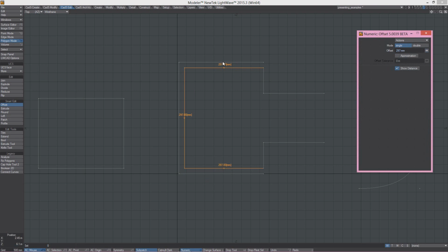Second way is to hold the Shift key on the keyboard and click and drag the mouse from left to right. That way, holding Shift, we adjust all selected or active selected handles. Because when we deactivate some handles, we are adjusting only the selected active handles. And the last way to adjust handle values is to click directly on the handle and adjust it without the Shift key. So these are the three basic ways to adjust active handles.